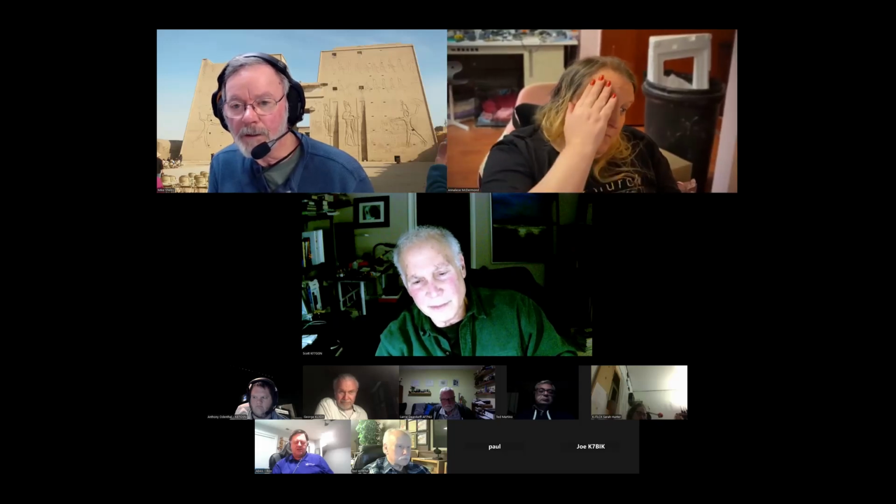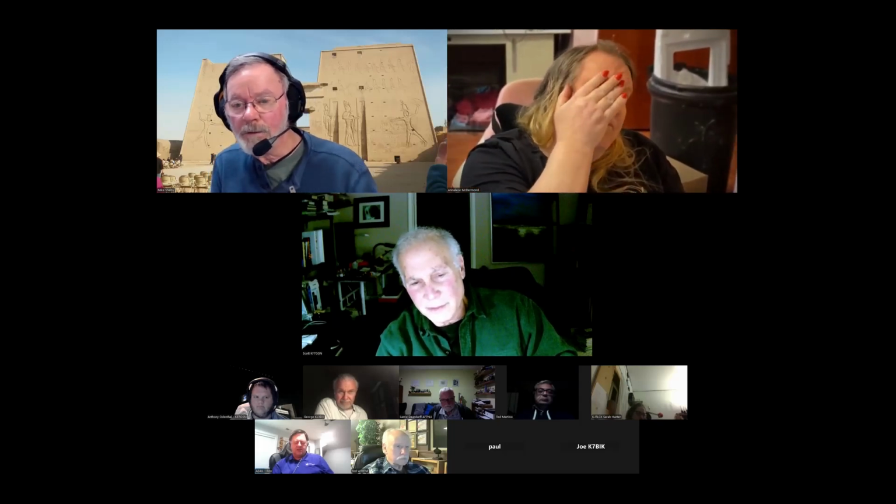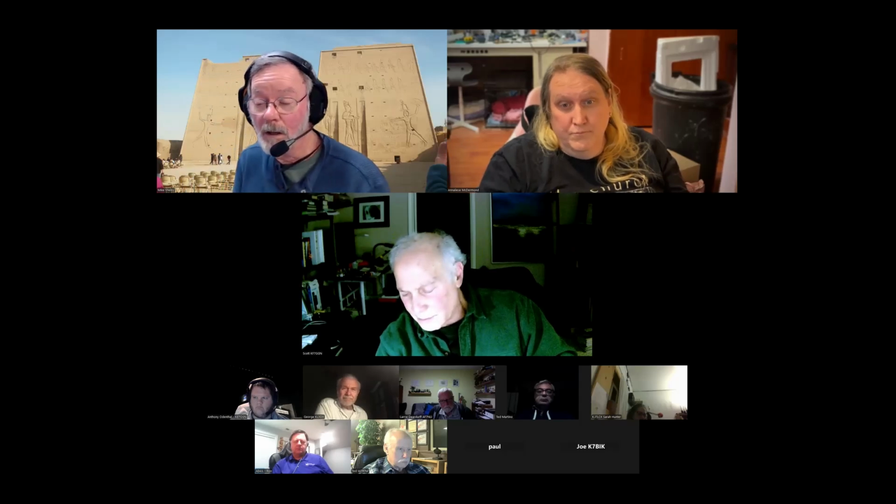Yeah, every week on Monday, actually tonight. Is it Monday or Tuesday? I have to look on my schedule. But anyway, Monday or Tuesday night on 2 meters, there's a group of guys that get together where they talk from here over to Central Oregon, up to Seattle, down to Medford, Roseburg. It's pretty good, and it all depends on the conditions. They can't do it every week, but that's what they use for all their horizontal. I tried using vertical and I couldn't even get in their ballpark. But flip it over to horizontal and yeah, I could hear those guys.